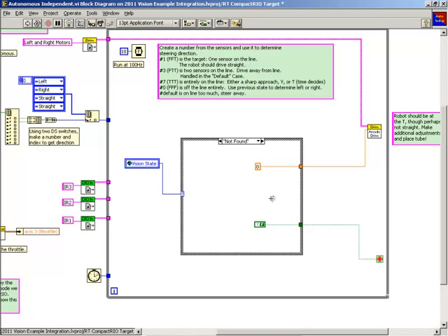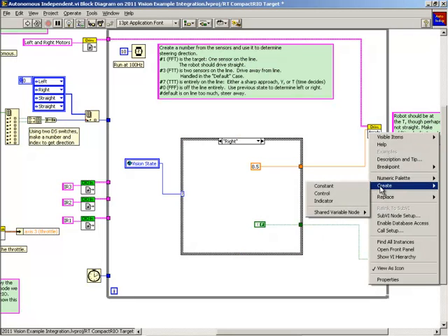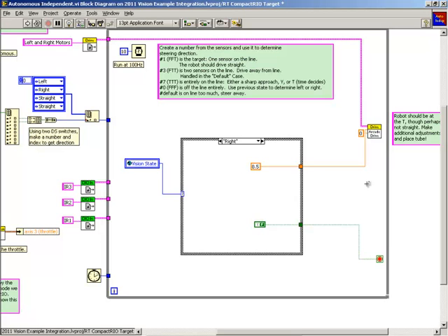Note that we could also tell the robot to turn in either direction in this case, so that it might find the poles. We will set the loop condition terminal to false, to continue running the loop in case the camera finds the leftmost pole again. In the right case, we will set the x-axis value to 0.5, because the leftmost pole is to the right of the robot, and so it should turn to the right. We will set the loop condition terminal to false, to continue running the loop. We want the robot to align itself with the leftmost pole, not to travel towards or away from it, so we'll create a constant for the y-axis value of the arcade drive function and set it to 0.